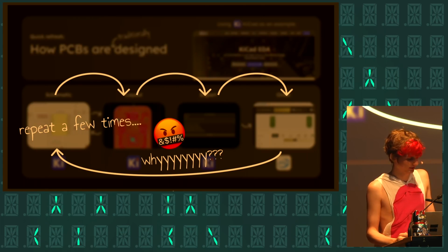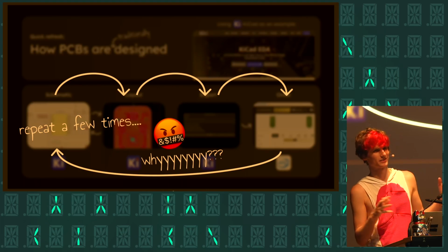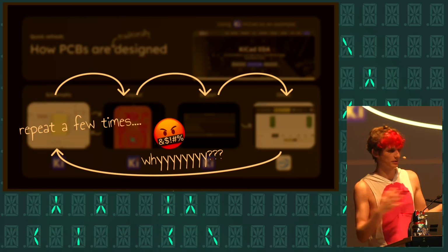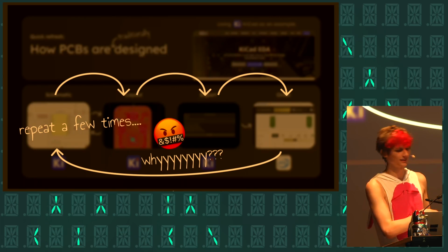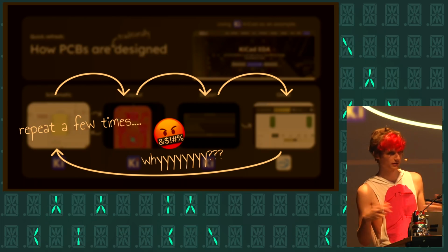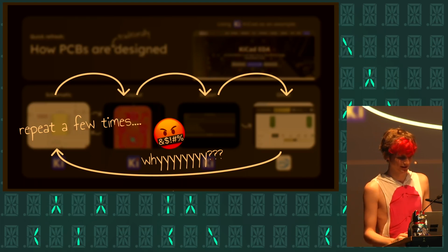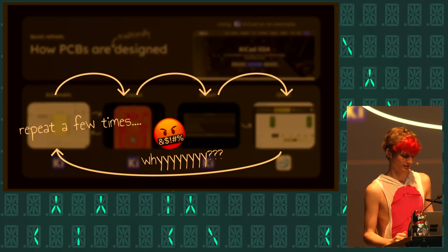Yeah, maybe I'm processing a bit of a trauma here, but what I learned from that is to ideally design your circuit boards in a modular way. Instead of directly combining everything together, first, for example, if you have USB power delivery for getting power, have a separate module for that and test that first. Have one for power conversion if you need that, and then connect them step by step instead of having everything connected together, because you probably think you're going to save money, but then you don't, because you end up needing to buy more PCB variations.